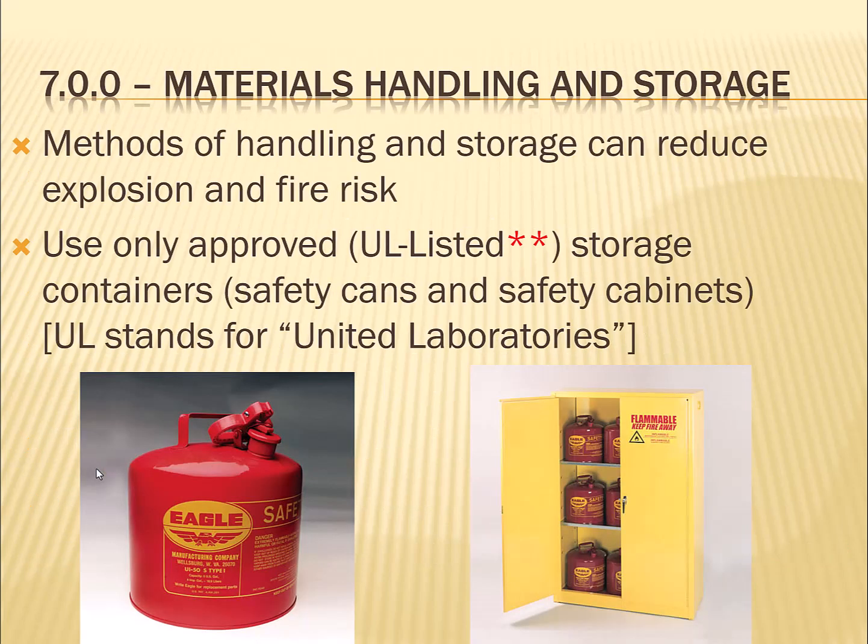Anyways, so let's see. So storage of materials. So an official gas can should not be made of plastic. Now I know I've got some around my house, especially I've tucked some in my attic ready to pull out whenever there's a hurricane coming. So I'm ready to get some fuel for my generator. But on your job site, you shouldn't be playing around with plastic gas cans.